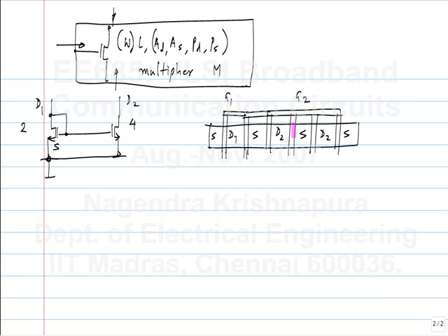Transistor gates. Now, this whole fabrication process also depends on how one particular thing gets fabricated. It depends on all kinds of mechanical and electrical behavior of what is around it. So, it turns out that this particular transistor will have slightly different characteristics from the ones in the middle. So, in addition to doing layout like this, you also end up having dummy fingers, one or more of them on either side. So, depending on the degree to which you want to match, you at least have one on each side. Okay, and these are not connected anywhere. These are like unused transistors.